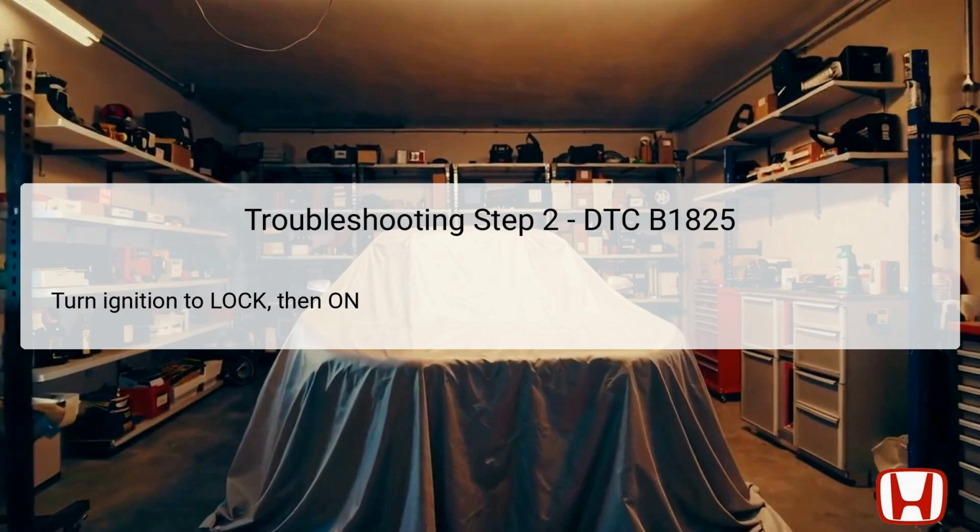This step acts as a bridge between the clearing of codes and exercising the power seat functions. Following the ignition reset, you need to operate the power seat adjustment switch for several seconds in both the forward and backward directions. This action is vital as it stimulates the power seat's operational capability and translates into real-time feedback for the seat position sensors.